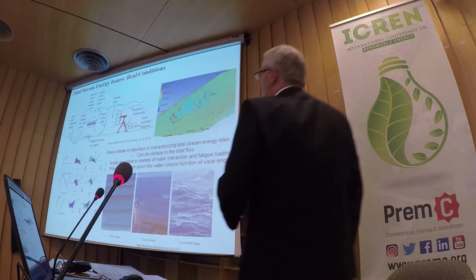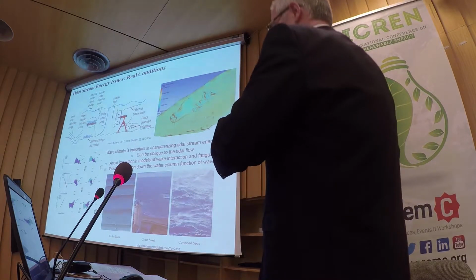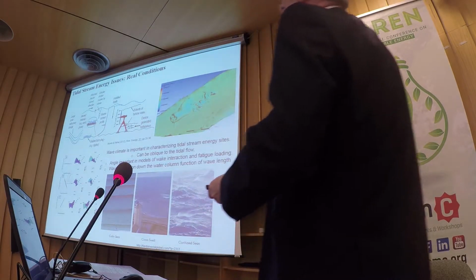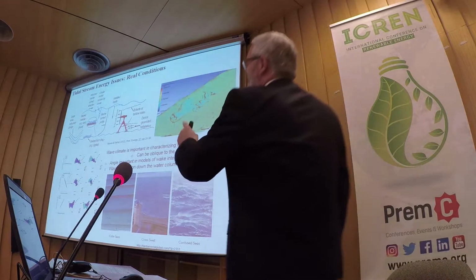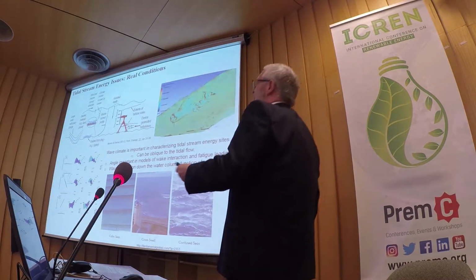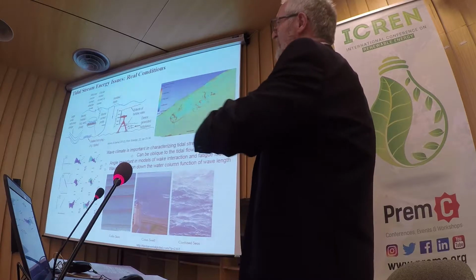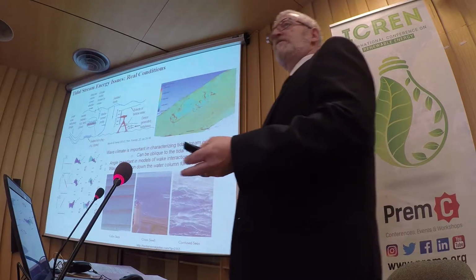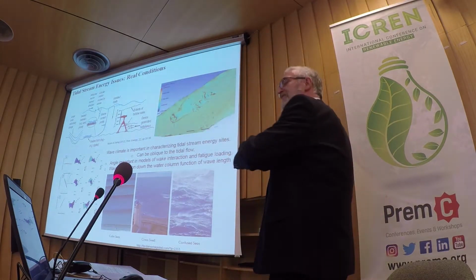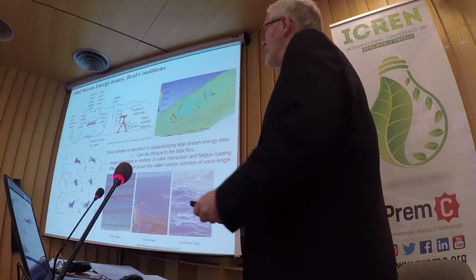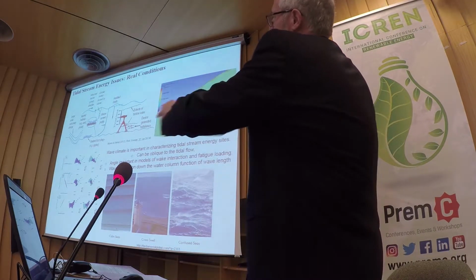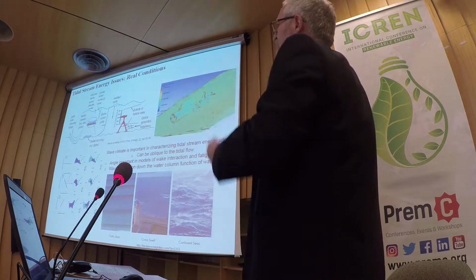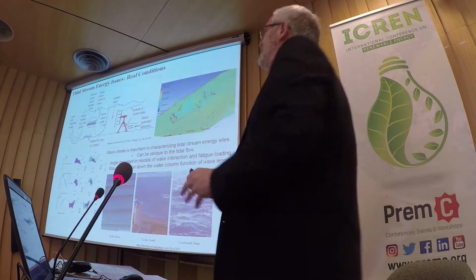So to break it down, I will quote from our friend Professor Bahaj, who published this very nice little schematic. Turbulence can be started from either headlands upstream, it can be due to the seabed. If you've got large lumps and divots, it can form very large eddies. If you've got a very rough seabed, you can get a higher amount of drag. That higher amount of drag will actually produce that current profile. And the bigger the profile, the worse you're going to get for any asymmetric loadings.